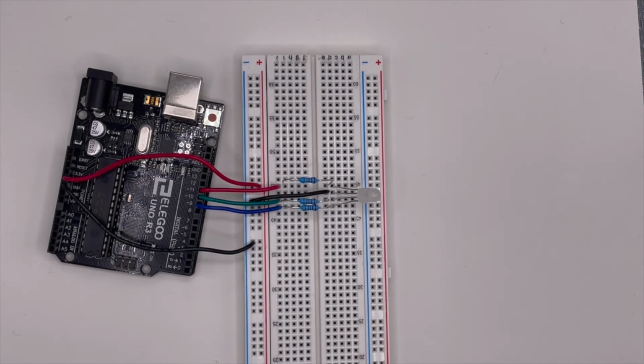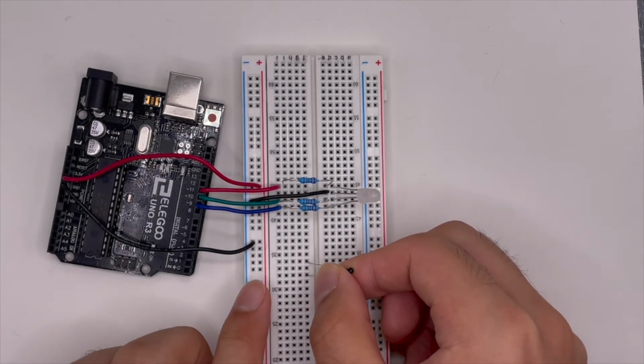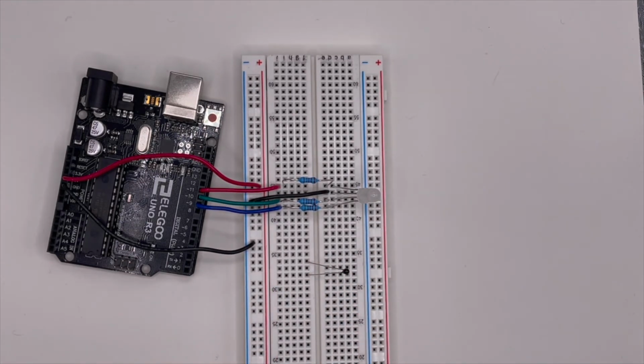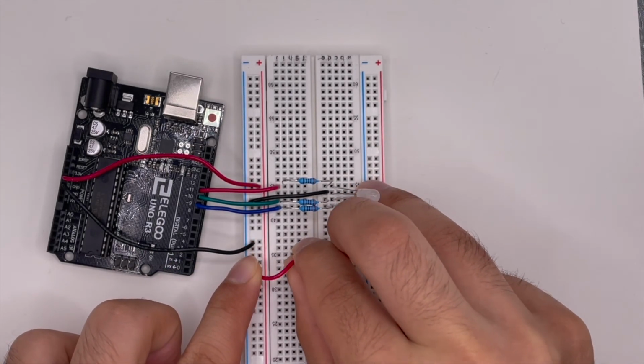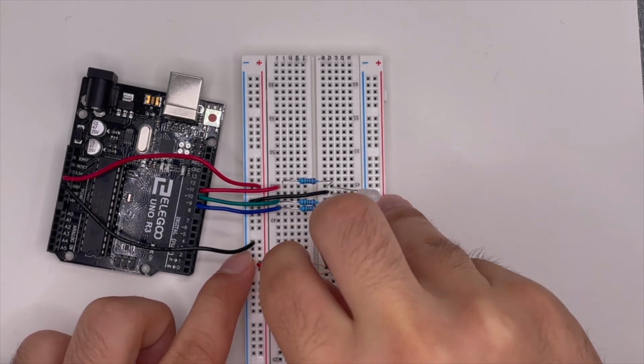It functions as a resistor, so the order doesn't really matter. So we can just place it like this, just anywhere you want, as long as the legs are in two separate lanes. And of course, we need to power the sensor. So let's connect a power wire from the sensor to the positive bus line. So from here to here. So that way we can make a circuit through this.